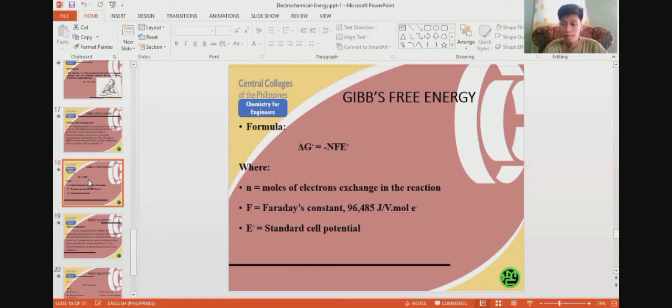applications. So first, process simulation of distillation process, estimation of activity coefficient, useful for models such as NRTL or non-random two-liquid, UNIQUAC or universal quasi-chemical, and the Wilson model. So the Gibbs free energy is also central to crystallization processes. So that is the application of the Gibbs free energy.